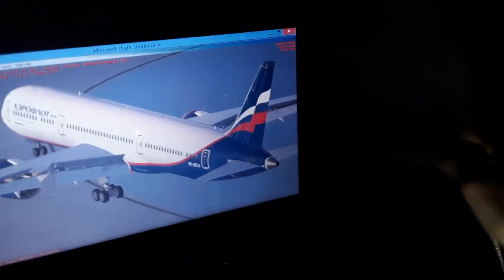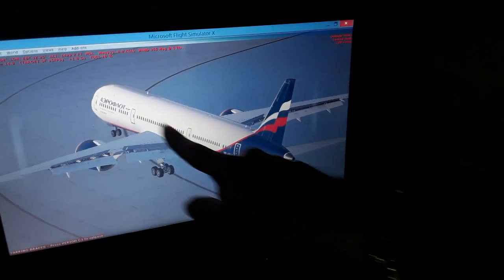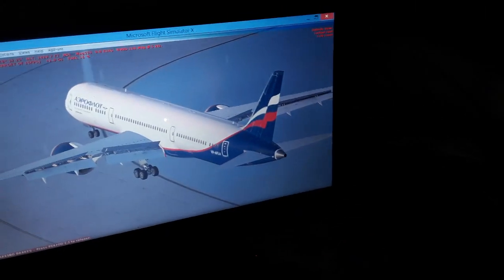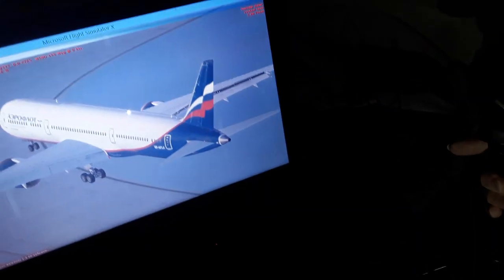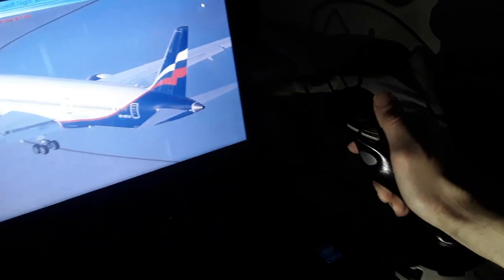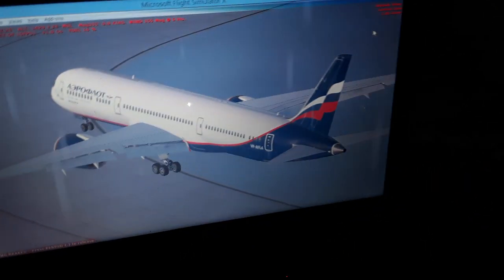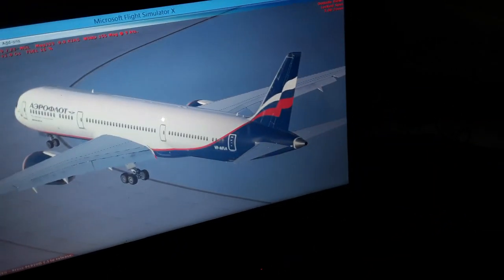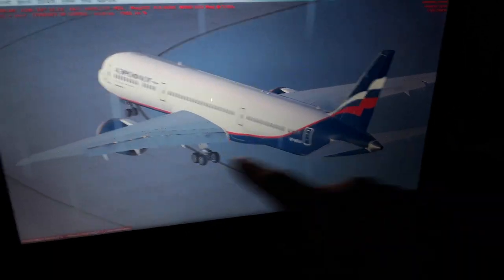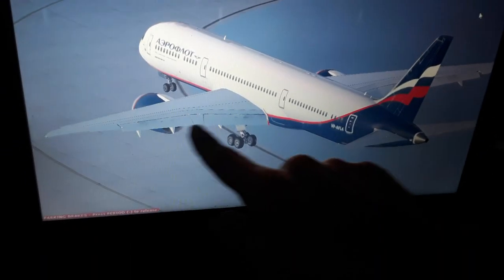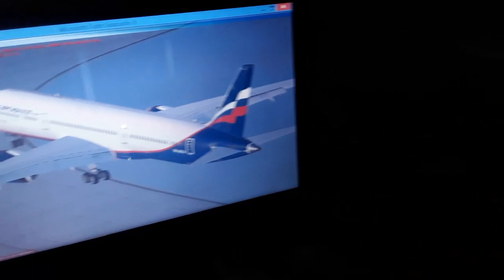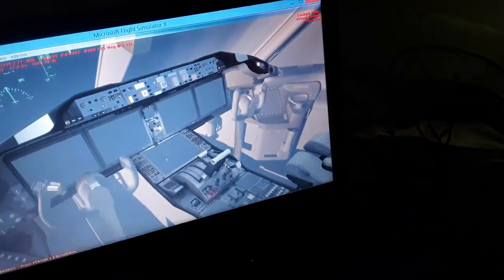Also in the Airbus and the Boeing aircraft, all aircraft actually, we have one more axis from nose to tail, the longitudinal axis. We can make left and right turns using the side stick in the Airbus, left and right, or in the Boeing we use the control wheel. We use the ailerons and the spoilers to produce aerodynamic lift difference between the left and the right wing. In the Boeing also we have the aileron spoilers and the flaperon. So we have aileron spoilers and one flaperon here and on the other side. So side stick left and right turns, both Airbus and Boeing. Same flight controls, no difference.